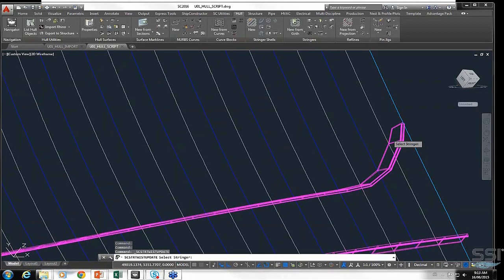An individual asked how to split the stringer if we want to. The stringers can be cut or split with native AutoCAD curves. And so that you can actually, oh, there you go. So hull stringers, yeah, the stringer can be cut or split with native AutoCAD curve splitting functions in hull. So that's one way that you can split it. And the stringers in hull are based on polylines, so that's why you can just split them that way.